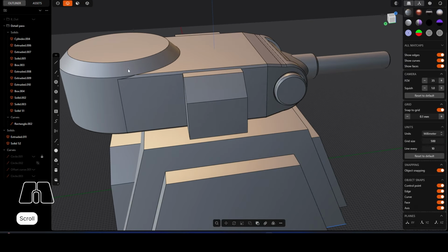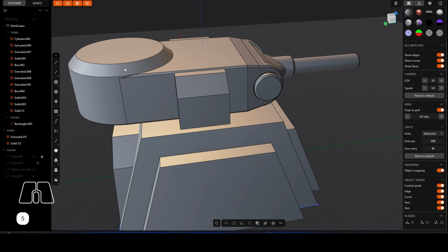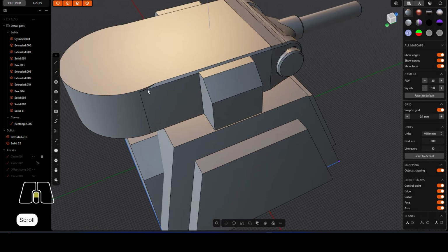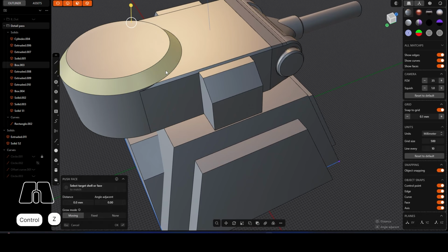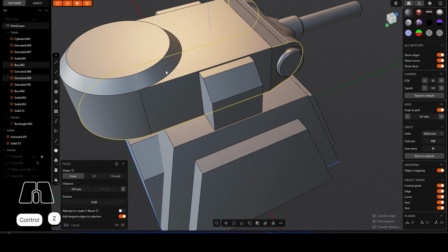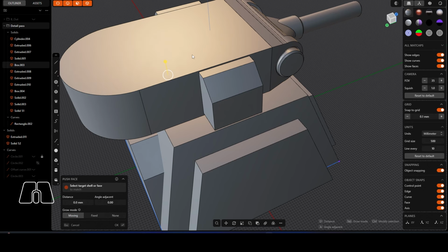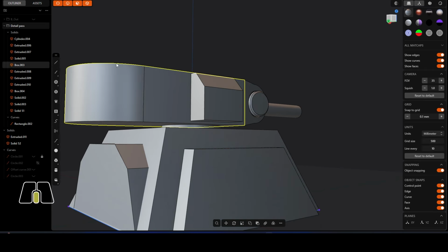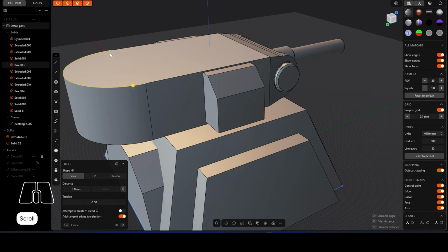And what we can try and do is maybe if we use the 5 key, grab this, let's use X, we should be able to get rid of that. Let's have a look. Is it not? Okay. Don't want to get rid of it, so we just bring it down like so. So what I might actually do is let's just go back. I'll grab this bit. Let's just merge it down because we can redo this. I'll re-grab those edges because I liked that running detail around it. I thought it was quite nice. So we'll grab these again.